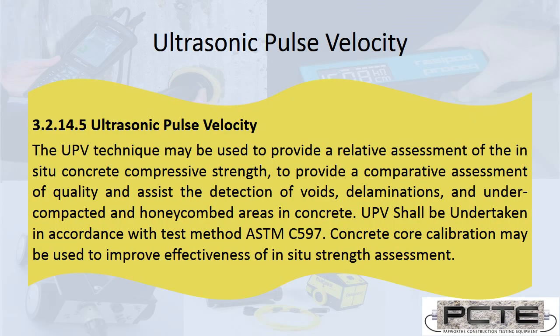Moving on from the corrosion investigation tools, I'm now going to start talking about sonic testing tools. Sonic testing tools are most sensitive to the voids and damage in concrete. So where we use an ultrasonic pulse velocity test or an impact echo test, these are the better tools for finding voiding or damage, and also in some cases for things like measurement of thicknesses.